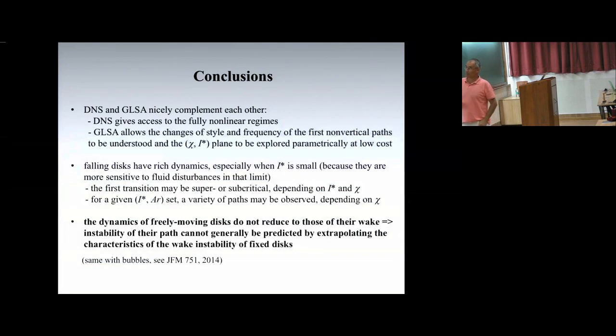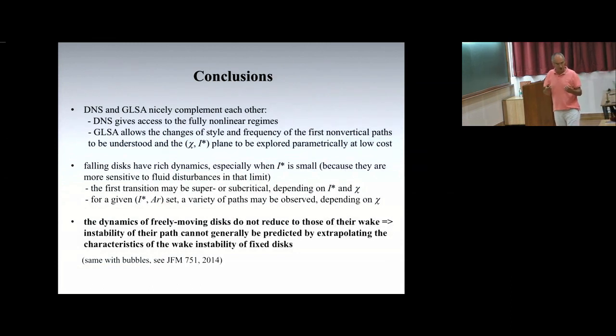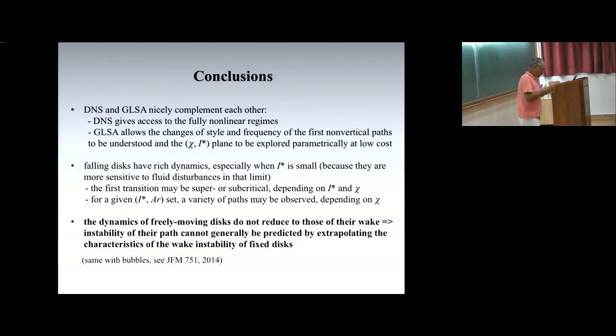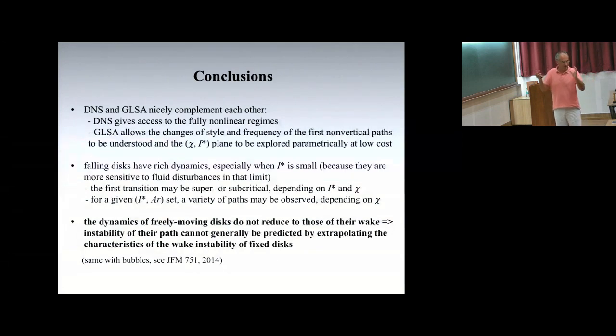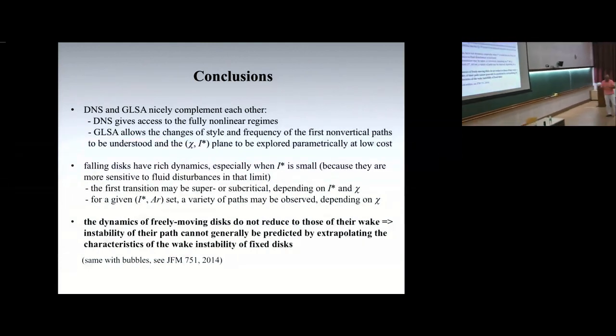The second point is, of course, that falling disks have a very rich dynamics, especially when they have low inertia, because at low inertia, they are much more sensitive to the fluid. And as I said before, probably the most important message, and this is true not only for disks, this is true for any bluff body at least, is that you cannot reduce the dynamics of a freely moving bluff body to the dynamics of its wake. The wake is very important.